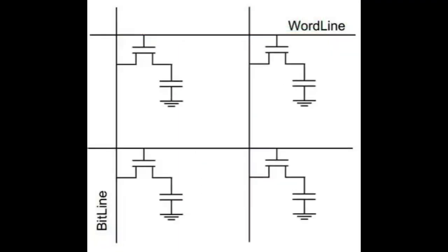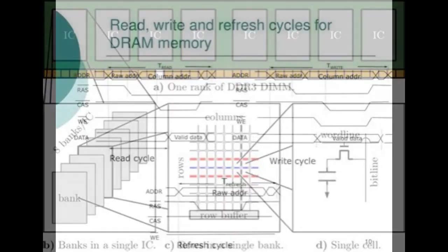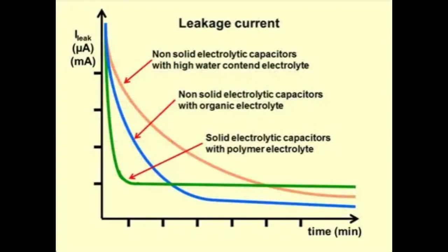Now, modern computers often use DRAM, aka Dynamic Random Access Memory. Each bit of data is stored in a tiny structure called a memory cell, made from one capacitor, which stores charge equals the bit. One transistor acts as a gate to read/write the charge. This design is called 1T1C. A charged capacitor represents a 1, and an empty capacitor represents a 0.